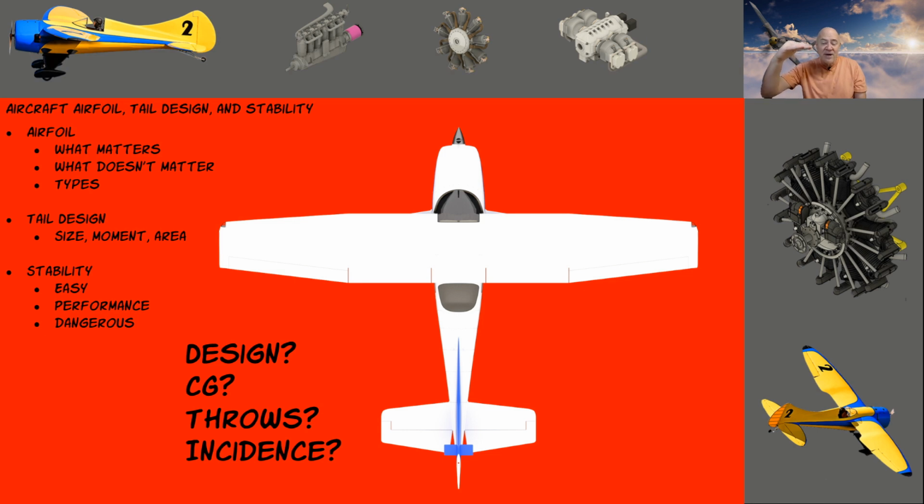He actually had about 1.5 degrees, I think it was, on the whole horizontal stabilizer. The nose of it was down, so it was making the plane always want to climb. So he had trimmed in down elevator, and the plane flew fine because the CG and everything else was good. And it wasn't worth cutting the tail off and fixing it. But I will tell you one that had to be fixed. My MSL-1, my vintage airplane with the sewn-on fabric with all the rigging, on the test flight, the plane flew with an attitude like this.